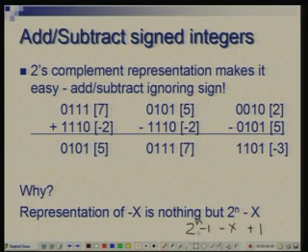So 2 raised to power n minus 1 is all ones, okay. So you subtract a binary number from all ones, basically each bit will get flipped, right, and then you are adding a 1 later on. So this just shows the relationship between two ways of looking at it.